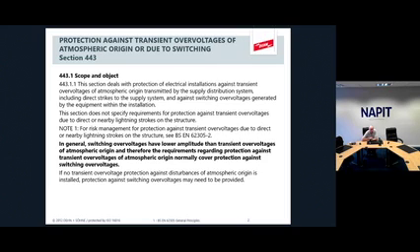There's also reference there to another standard, 62305. We'll have a look at that as well. That's the British standard for lightning protection. And the two standards do dovetail together if you're working on larger installations and structures. And also, if you've taken measures to protect against transient overvoltage of atmospheric origin, also known as lightning, that pretty much means you've probably covered the switching overvoltage events as well, but a little bit more about that later on.